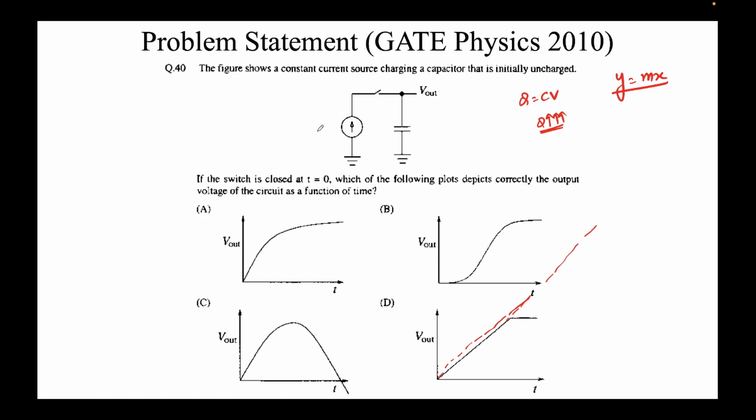The other way of saying it is that you can look at the current source over here. These also operate at some voltage. You see that this node voltage will keep on increasing, right? All these current sources, which you'll see in a question today itself, cannot operate above a certain voltage, because this current source is usually driven by a BJT, bipolar junction transistor circuit, and every BJT circuit has some voltage provided to the collector, let's say VCC. So the voltage across this current source cannot be arbitrarily high.